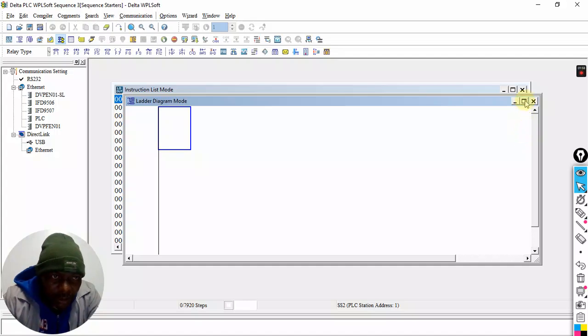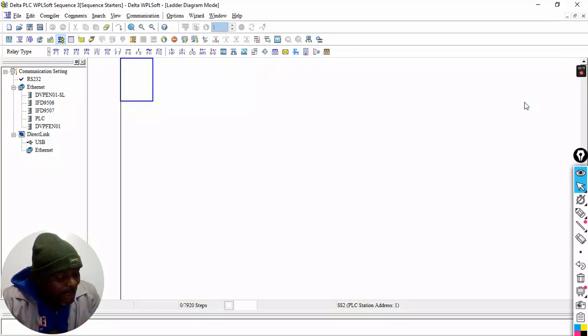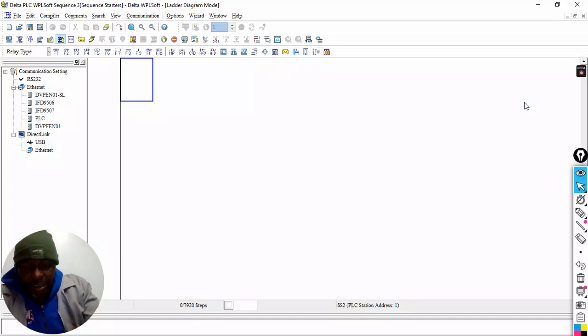Please take note or write it down. I'll read it slowly. When the start button is pressed, motor K rotates immediately. After 10 seconds, if you press the same start button, a second motor should start. Then after a further 10 seconds, both motors should stop. And then you have your two overloads, your emergency stop, and your stop disrupting the whole circuit.